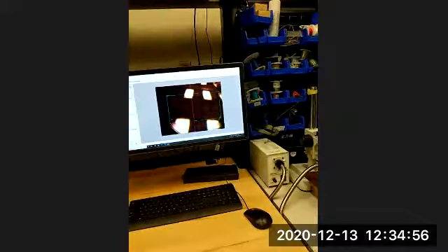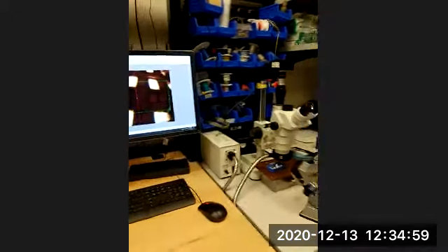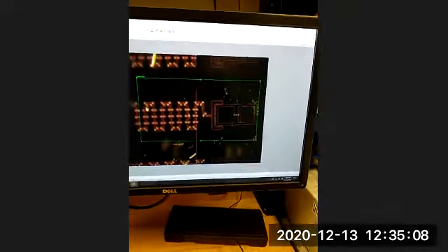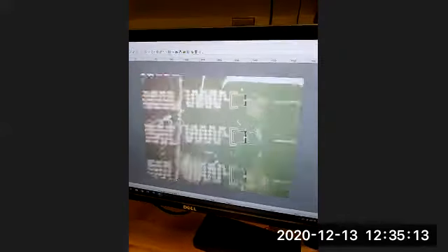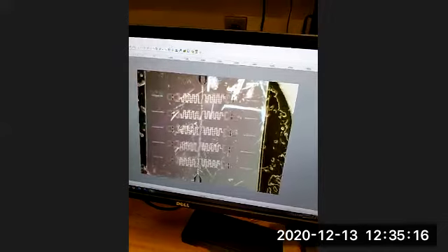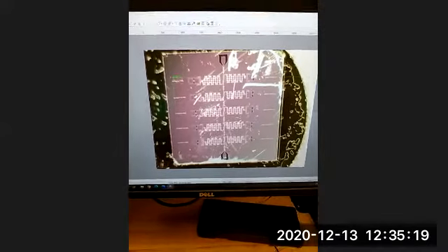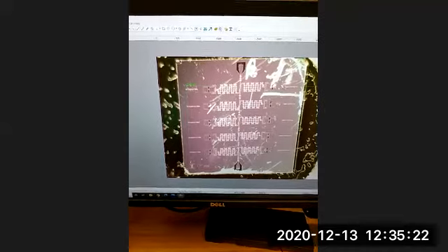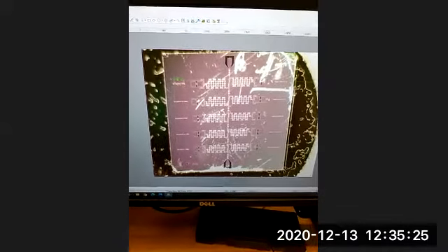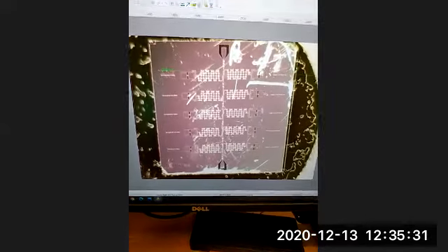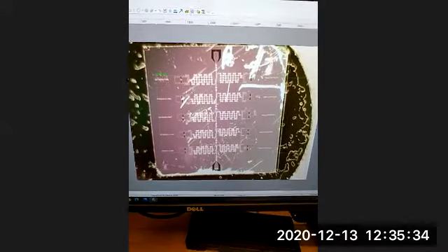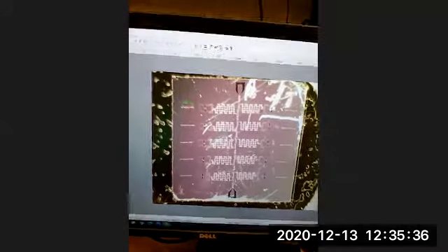And what I'm going to do is show you this optical microscope that will show us, hopefully, one of our superconducting qubit samples. Live demos are never a great idea, but let's see if we can get it to work. All right, great. So there it is. What I'm going to do is zoom out first. Okay, so what I have in the picture here is a 5 by 5 millimeter little chip. It's made of a substrate of silicon and a bunch of evaporated metal on top of it. And there's a lot of scratches on this one, so this one's probably not going to be a very good qubit, but I'll just break it down for you.